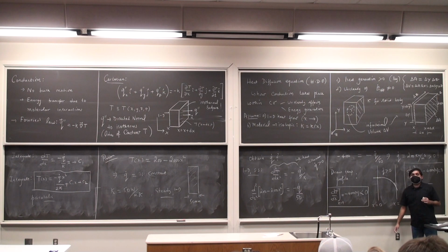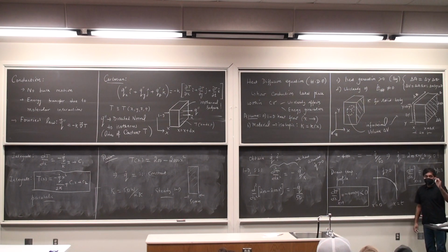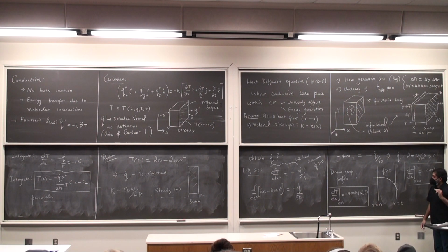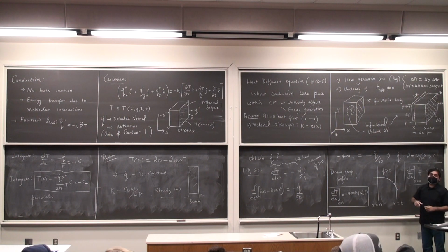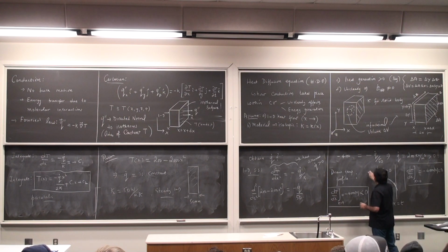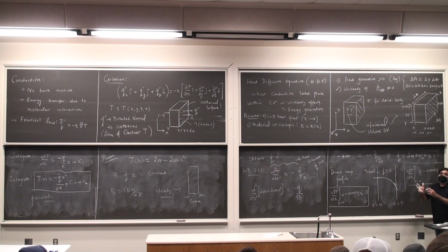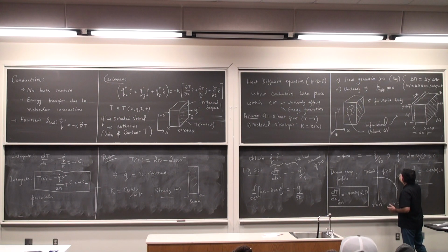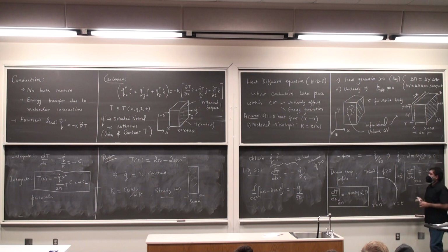And it is really important to understand how we obtain this. Once again, I have 2 more minutes left. Once again, temperature at this side is 200 degrees Celsius. How did I get that? Just by substituting x is equal to 0 in the temperature profile that is given to me. No big deal. Temperature at the right hand side is 195, which I also obtained by substituting x is equal to 50 millimeters in the temperature profile equation.